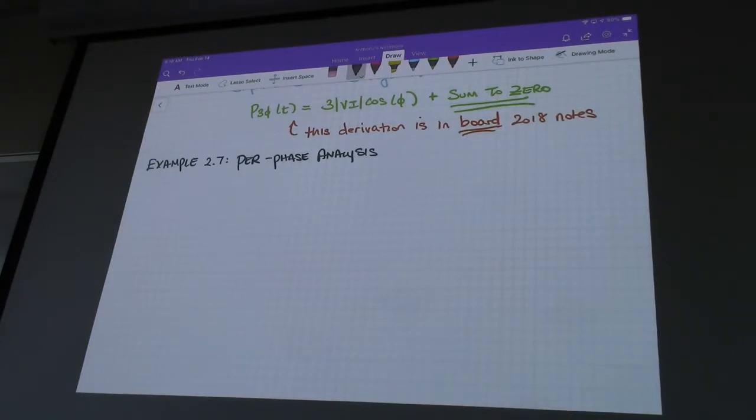So I would be prepared. As I said, I'm going to get the homework worked out, the assignments. But be prepared for a three-phase system given to you with Y and delta connected loads, Y and delta connected voltage sources, being able to convert everything to a Y connected form, solve the single phase analysis, and give me the values in three-phase.